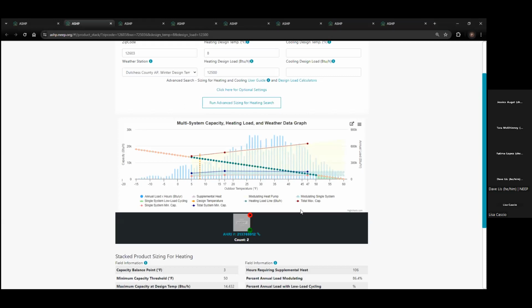However, if this is a single one bedroom, one bath apartment, and one heat pump head is in the living room, one heat pump head is in the bedroom, all you need to do is open the bedroom door and air will flow back and forth between the two rooms. You can look at these two systems together as if, in those really low load hours, one heat pump head will turn off and give primacy to the other heat pump head that will operate at its minimum and really low speeds and provide the little amount of heating that the space needs, while the other heat pump should remain off.